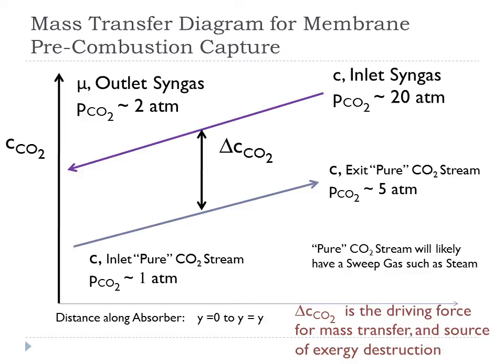And then what we'd likely do is, once again, sweep with some steam, or something like steam. The reason I've been mentioning steam here is that you can now cool off the gas and the steam will drop out, leaving you with the full total pressure being then the carbon dioxide. So that's one nice thing about sweeping with a gas that can condense out after you cool it.